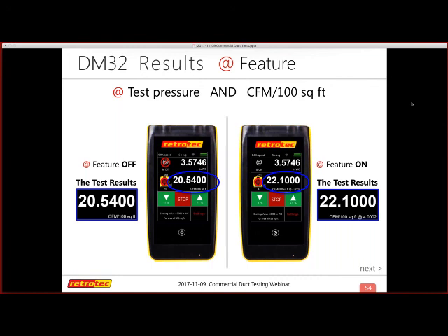But for commercial, we don't use set pressure, we use set speed. When you turn on the add feature, it goes to the preset settings inside the gauge, so the determined preset is what you've gone into the settings and determined. If you're going to test at 6, then you would go into the settings and make that 6 inches of water column.